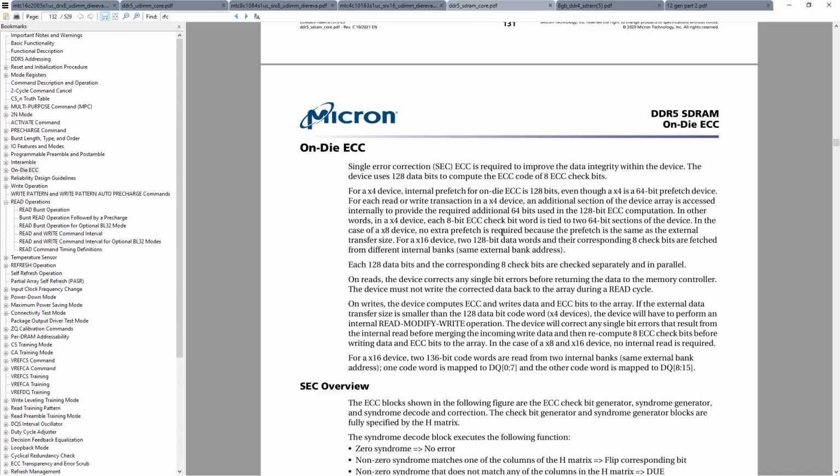But anyway, that's sort of what this is for. What this isn't for is, say, you send a 5 to address A, but instead of a 5 showing up, a 4 shows up. So you have a data bus error, right? Somewhere between the memory controller and the memory, the 5 becomes a 4, and the memory gets the 4.